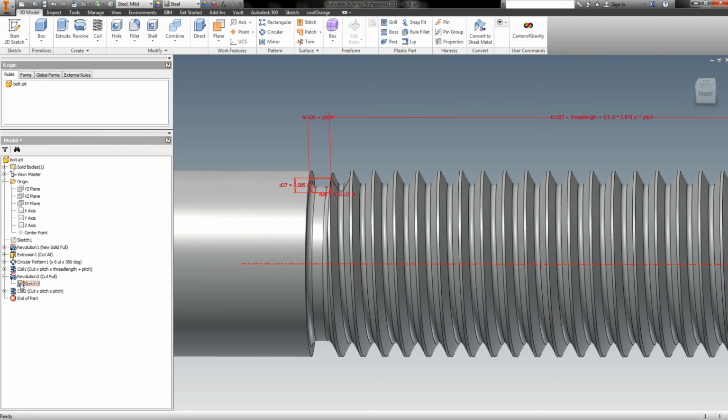Now this is just for a relief groove. This second coil, you could skirt it by just making the first coil longer, by adding the relief groove width, or probably divided by 2, to that coil length. But having a second coil also gives me the option, if I don't have a relief groove, I could have this coil taper as though it was tapered into the threads. And for the moment, I'm going to leave it as it is.